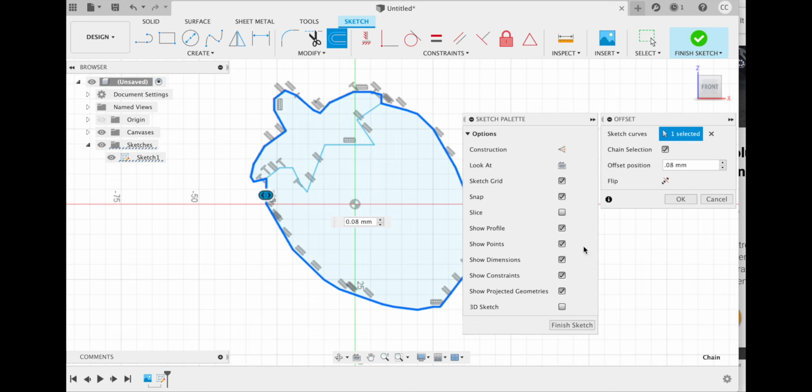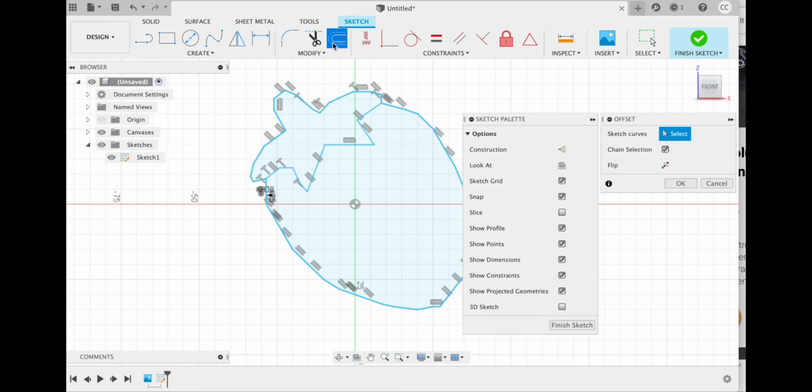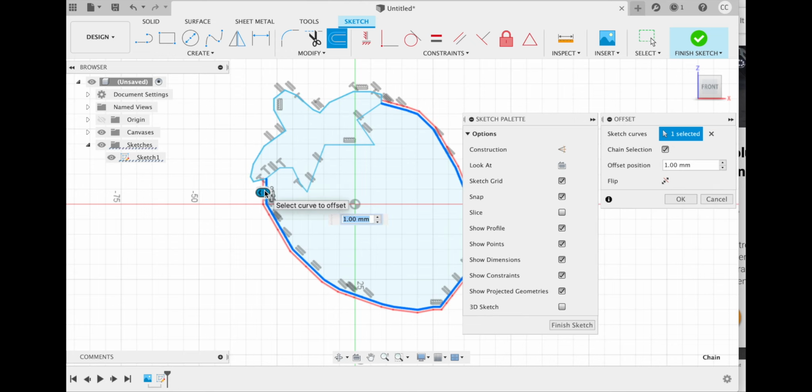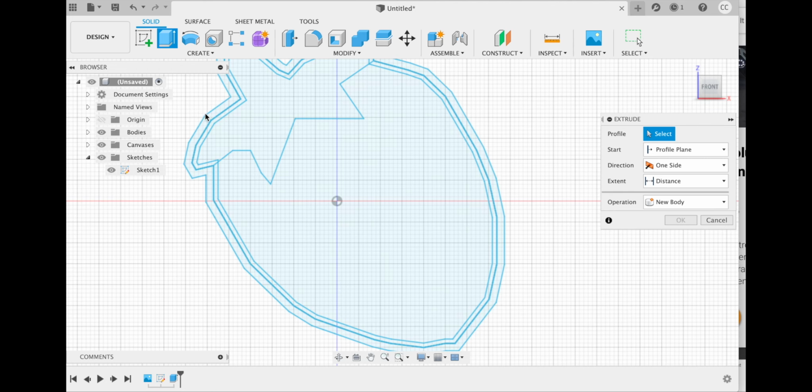But the second edge we're making on the outside, that's 0.5 to 1 millimeter, is going to be to extrude the shape outline of the cookie cutter, because if we don't have a good thick one, it's not going to be good enough to print. It'd be too thin of a wall for the printer to use.